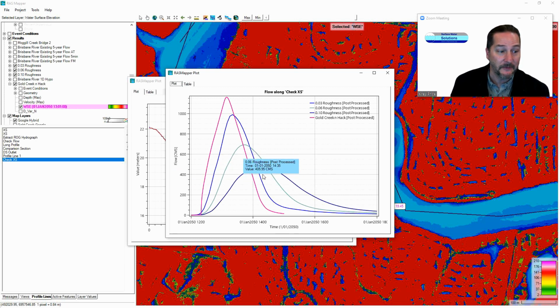If what was making it flow down in this area is maybe some interflows or something like that, and you are trying to manipulate overland flow to behave like interflow, it's really hard to match all three things at once: the timing of the peak flow rate, and the volume under that curve, all in the same model run. That's pretty tough to do. So we've got to still acknowledge the limitations of the model.